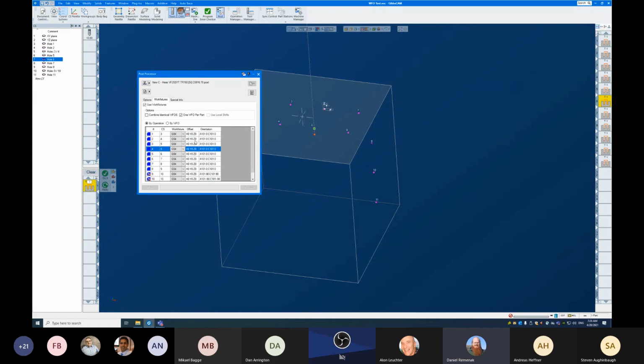And then the last big advantage of this is that you can actually see what's happening. So you can see, hey, all of my work fixtures are set to G54. I'm getting all origin output here. It's no longer invisible. It's no longer up to your post processor. It's now in front of you, it's controllable by you, and it's visible to you. Okay?